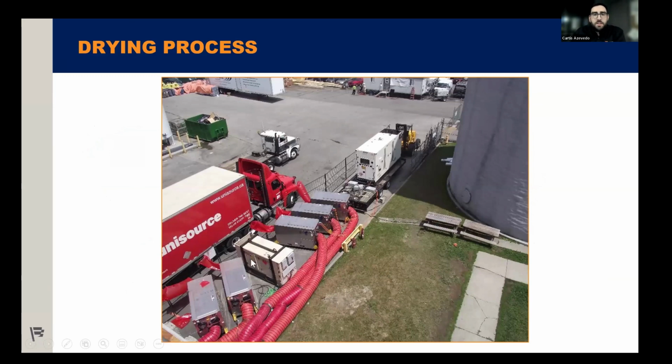The machines that we see here are really the most advanced dehumidifiers on the market. These are known as desiccants. You see lay flat tubing coming out of them, the red hoses on the one end. These hoses are taken and distributed throughout the entire building. So this was an apartment building, and essentially these hoses went one to basically every floor and then distributed throughout the ceiling, ensuring that warm, dry air was pushed through the entire space.